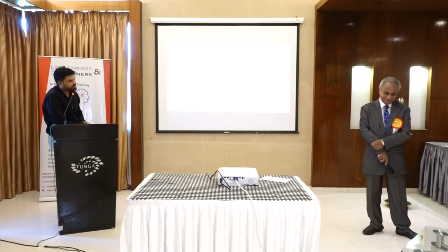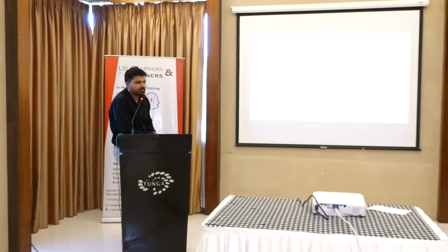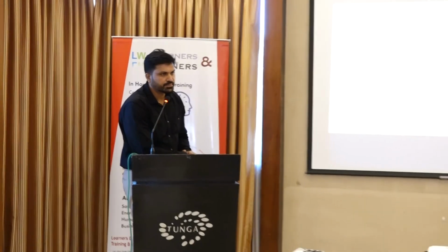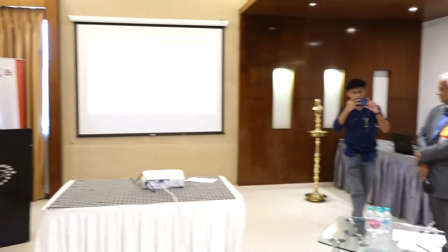And with lowers also we face this moisture ingress. And the dust will also go inside. Yes, there will be filters in the lowers. Most of the problems are erection problems, like heater cable coming in arcing distance. This is absolutely ridiculous. It should not happen. There was an issue of tripping because of that.